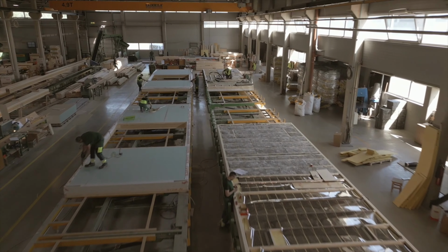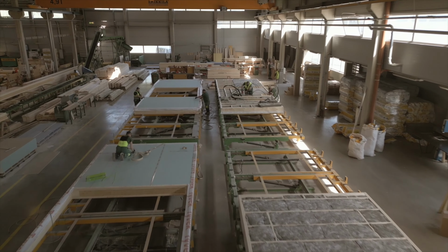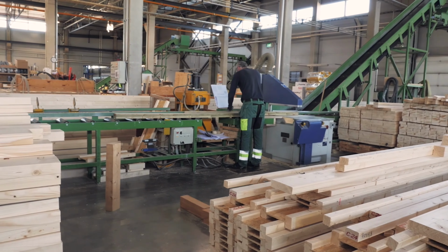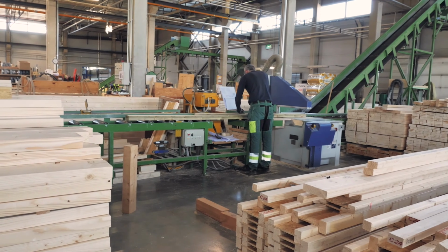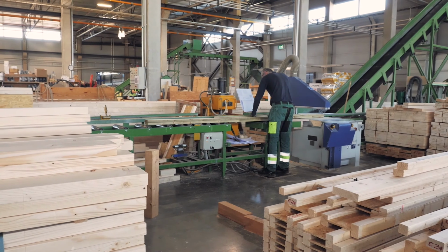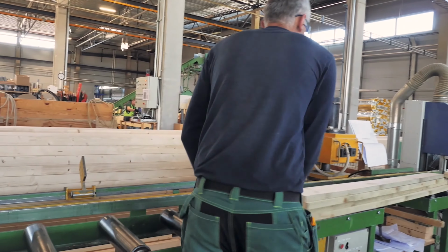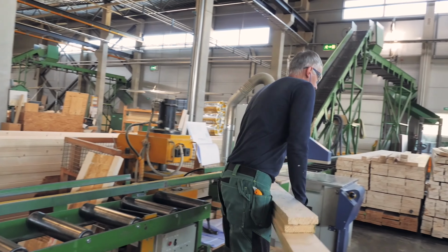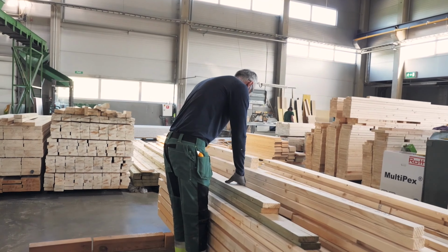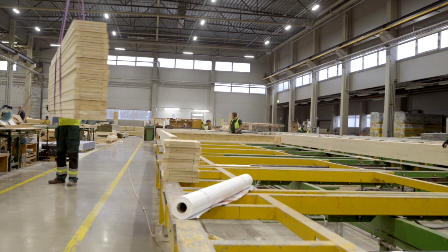Let's carry out the following floor assembly process steps based on the intermediate floor for the module. The assembly of the frame is preceded, as always, by preparing all the materials. If cutting the frame components, then do it according to the material specification. The table specifies the dimensions of the components and the quantity of pieces. Cutting is done either using an automatic machine or manually. Then, the framework is assembled on the work table according to the drawings.